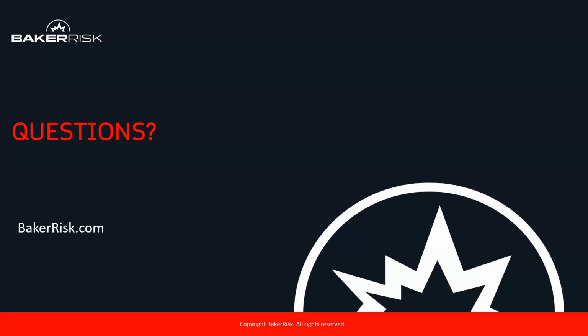So, as discussed, you may be performing PHAs throughout different stages of the life cycle. So, if you're doing a project and you have a very conceptual high-level design, you're likely wanting to use a methodology such as hazard identification. So you're identifying your basic hazards. If you have a very simple process that's already existing, you might not need the robustness of a HAZOP.